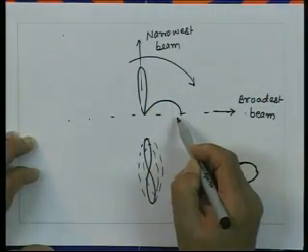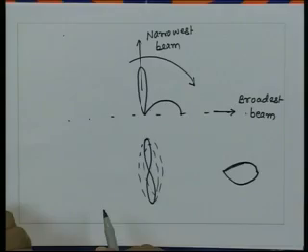Having understood this, one can go to the calculation of the directivity of these antennas in the 2 extreme cases, which are the broadside and the end fire directions. And then we will get something surprising, because looking at this, it appears that when the beam is scanning from here to here, since the beam is broadening, the directivity of the antenna is decreasing, because the half power beam width increases. However, this conclusion may be erroneous if we make it only on the basis of the planar radiation pattern. So, further we will investigate the directivity of the uniform array, and we will develop that understanding essentially by getting the 3 dimensional radiation pattern of this array.